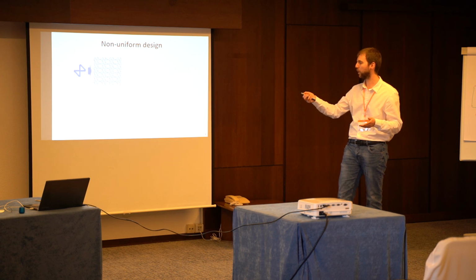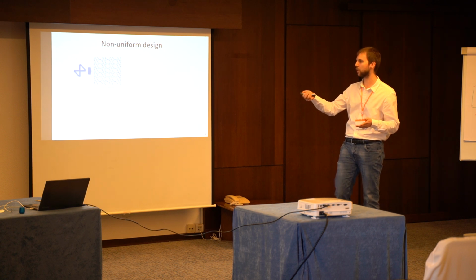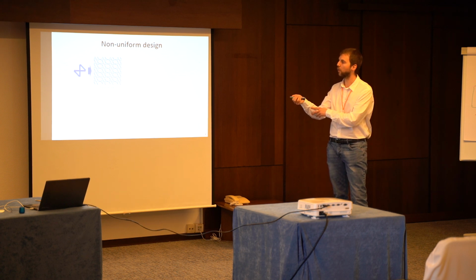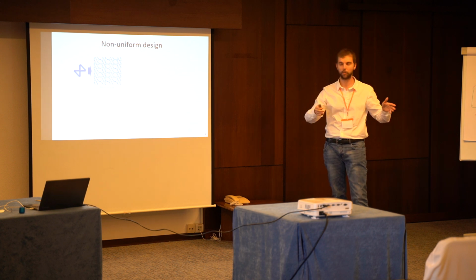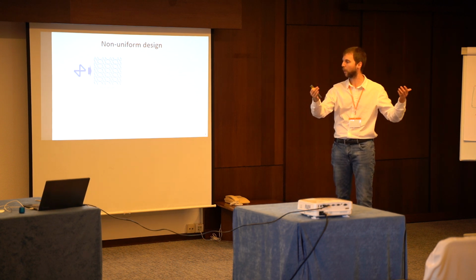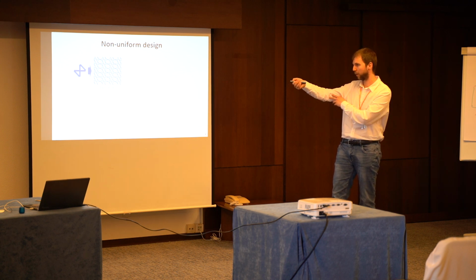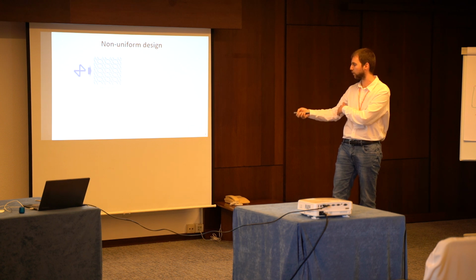If you consider one basic design as a unit, this is a uniform design, and you simulate it considering post-buckling. You tessellate an infinite plane, and then you perform post-buckling simulations. This is the post-buckling shape. You can notice some long wave phenomena along the 45 degree directions.